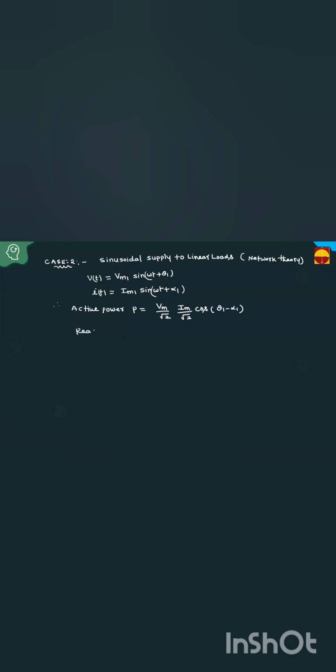How to calculate reactive power, friends? If two different angles are given, how to calculate here? Reactive power Q equal to Vm1 by root 2 into Im1 by root 2 into sine of theta 1 minus alpha.